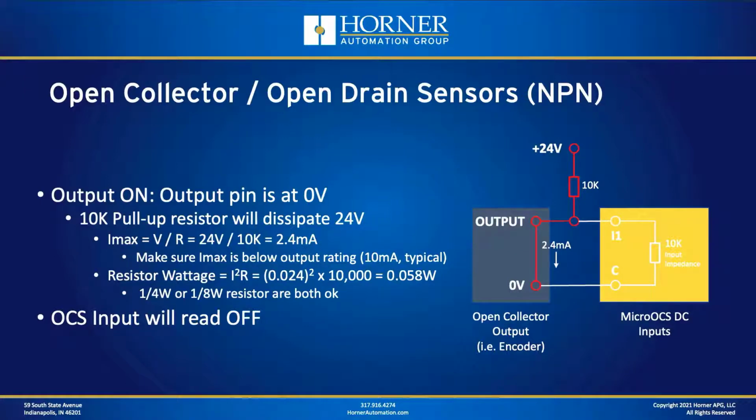That's basically how you would connect an open collector or open drain style sensor to an OCS when you otherwise have the OCS configured for positive logic. That can again be useful if you've got an oddball sensor like an encoder of some sort, for instance.